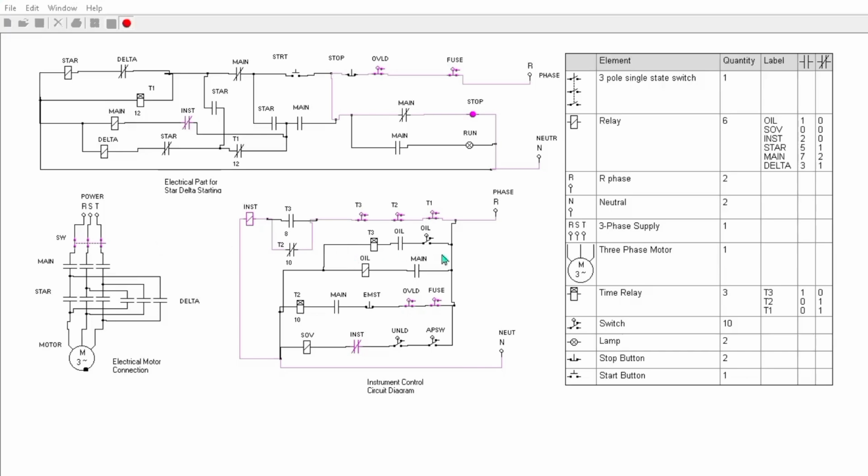You see we have said that there is an oil pressure switch. That means here is the timer, we used 10 seconds. Within this time period, if oil pressure is not available, the compressor will stop for safety. Now, for understanding, manually we close this switch.